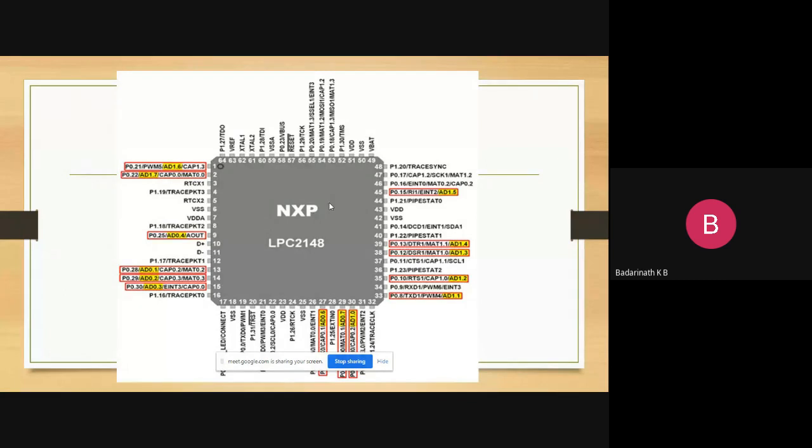to accommodate the different functions of the different blocks present inside the microcontroller like UART, SPI, I2C, GPIO pins are used for alternate functions. As we see the pins there, each of the general purpose pin, GPIO pin, has three other alternate functions. We call them the first alternate, second alternate, and third alternate function. For example, if you look at the pin 0.5, it has a first alternate function with SPI, second alternate function with a timer block, third alternate function with an ADC.